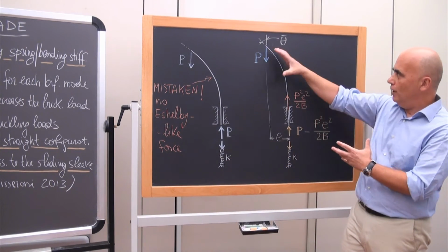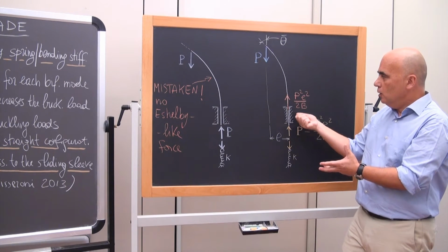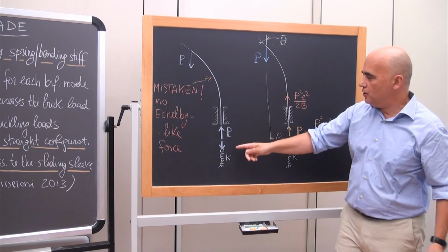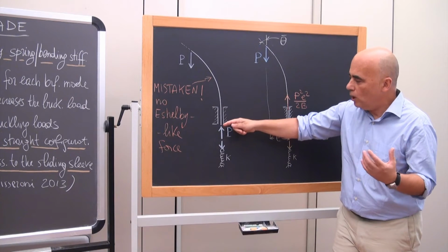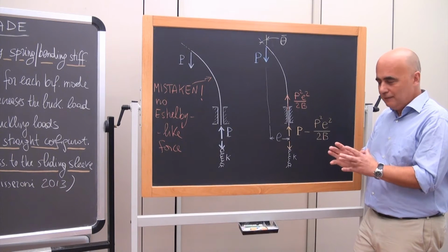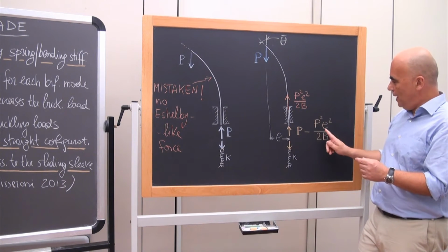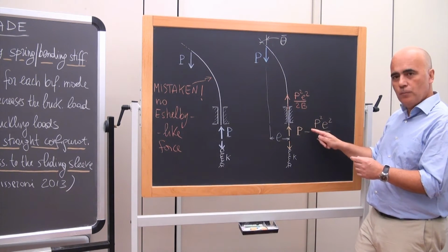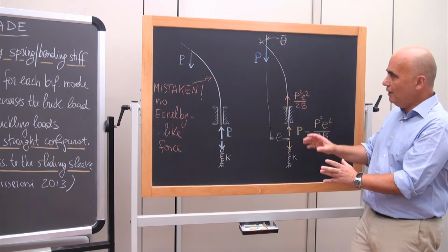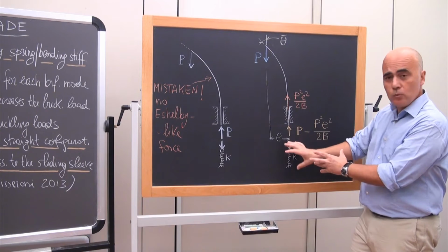And in particular, if we do an experiment with this configuration, we will see that this edge of the structure will move upward, which is strange because if we ignore this force, this part of the system will only go downward. So this feature needs special attention, and in particular the stiffness of this system can be arranged in a way to make this contribution identical to this contribution. In these special cases, this axial force will vanish, and so equilibrium of this system will be possible without any force here and therefore without any spring.